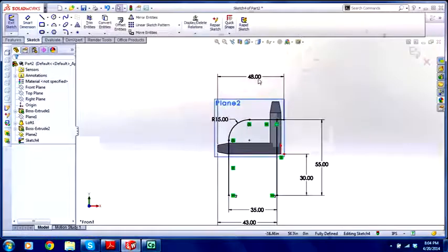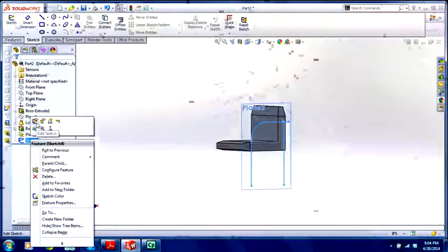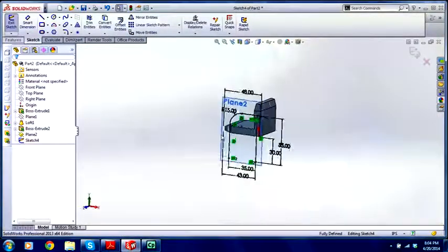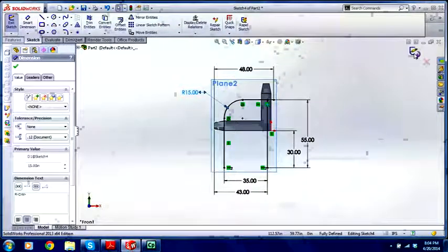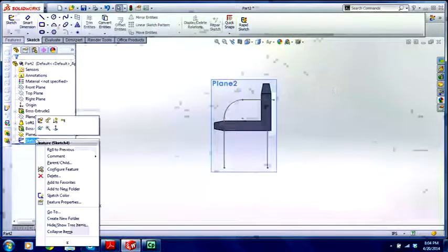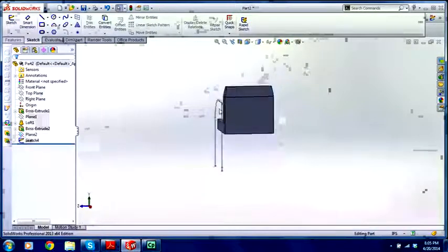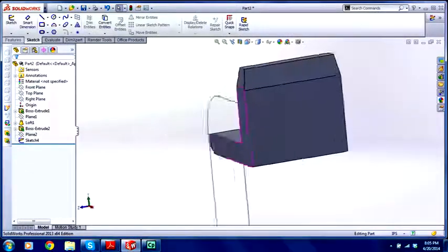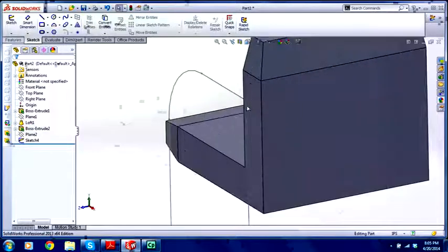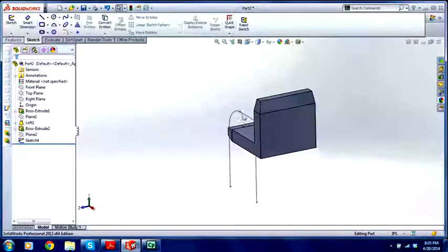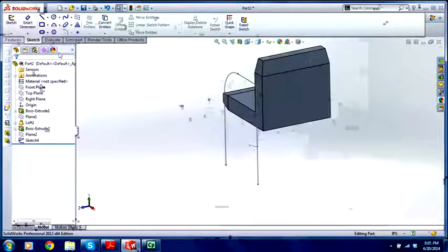That's it. Okay, I probably should put that up for a second or two so you can see it. I didn't use a 3D sketch, I'm just using a normal 2D sketch. Now watch this. No, don't turn it off, we need that. Let's turn off that plane. Look where it lies. Now I need to put a sketch. This is my path. I need a profile. So I need to put that profile perpendicular to any of those lines. It doesn't matter which one. It really doesn't matter.